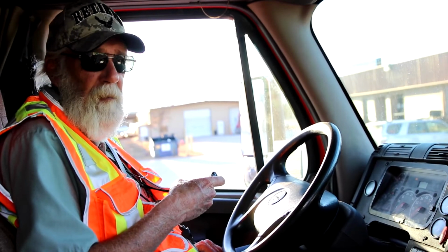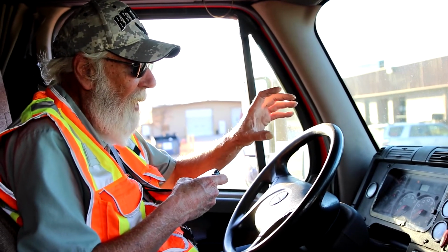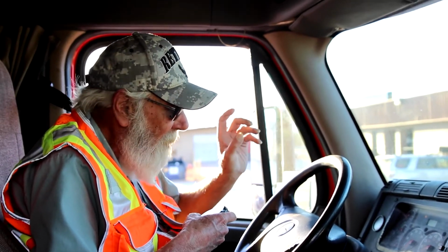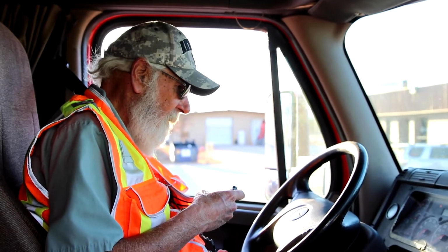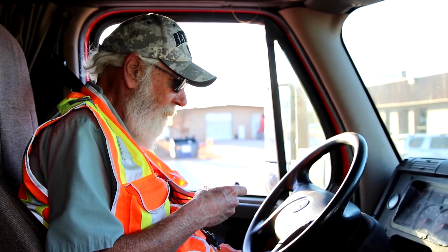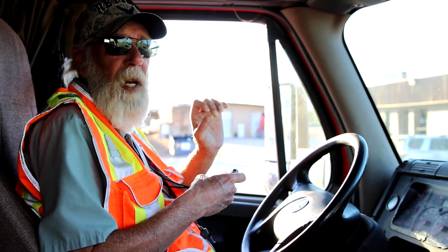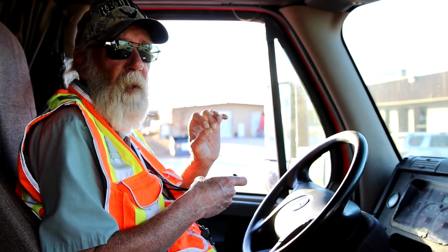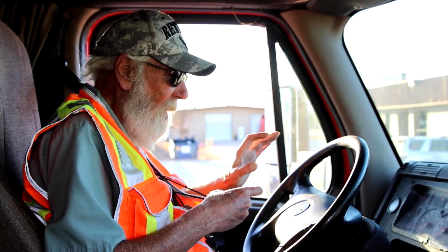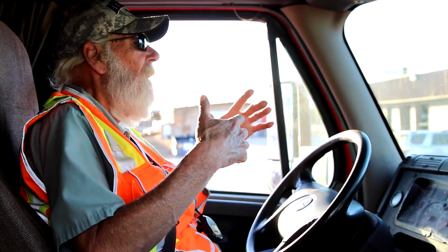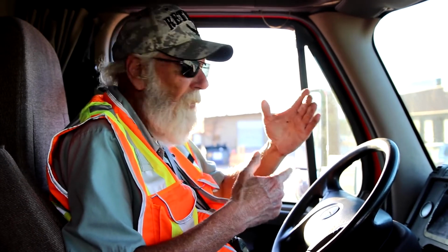Wait for 1 minute. Watching your air gauges, make sure you do not lose more than 4 pounds in 1 minute. I normally go about 1 minute and 2, 1 minute and 3 seconds. So, approximately 1 minute has gone. I went ahead and shortened it, but as a courtesy, I show the examiner my stopwatch. That way there's no confusion on the time length.